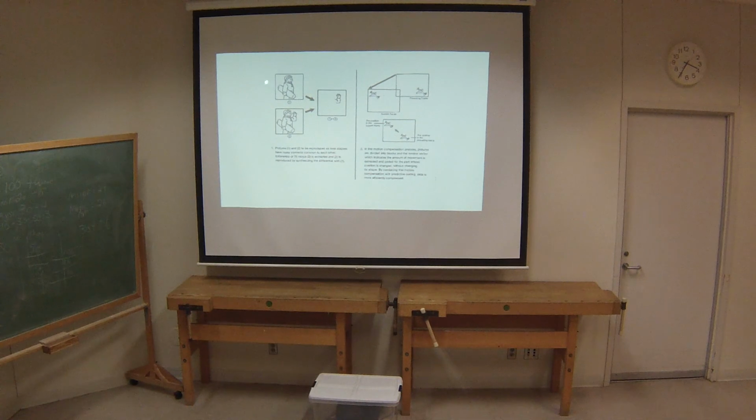this gives rise to the fact that when you do MPEG compression, you take a group of frames, generally at least 15, but it can be more. The first frame is your reference frame. You record everything in that frame, and it requires the most data.